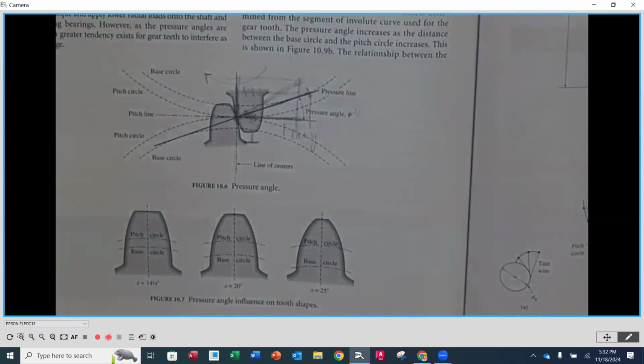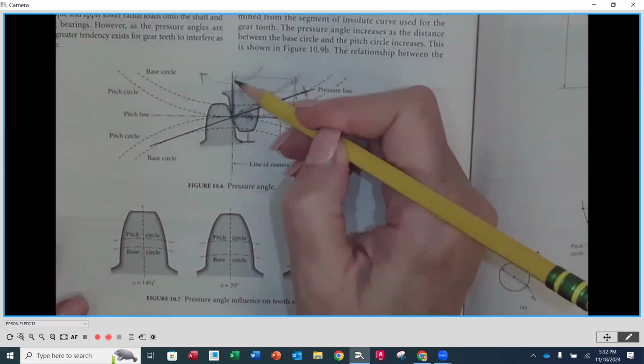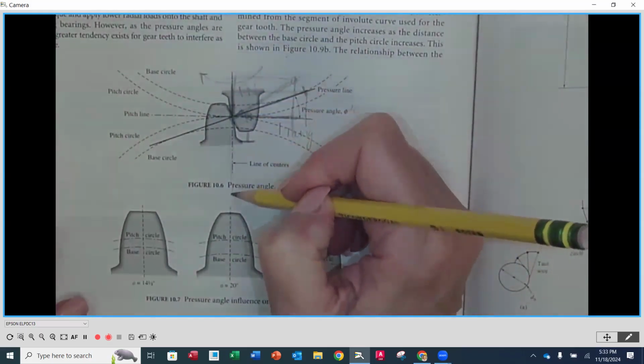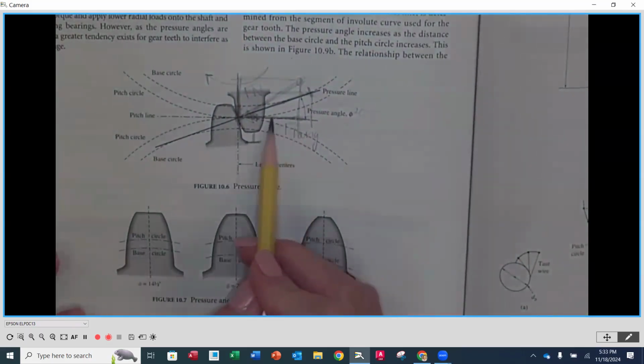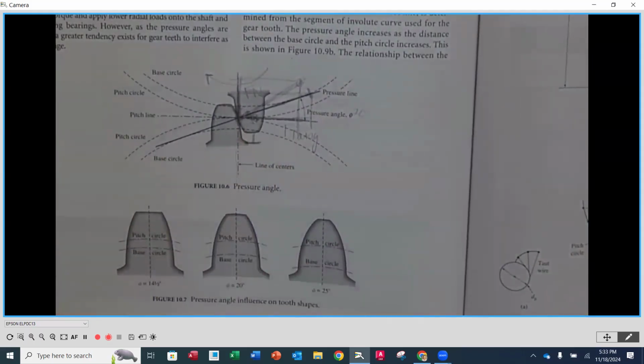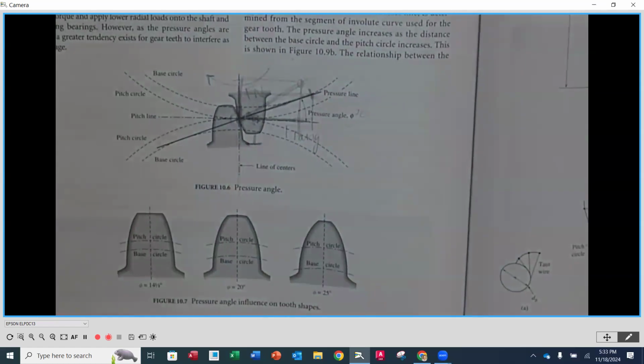The 25-degree pressure angle is reserved for applications where you have really large forces and torques that you're trying to push through, because you're sending more normal force down to the center of your gear where there's actual material, as opposed to putting more tangential force on, which is going to cause the tooth to bend over and the surface to pit away. So when we are anticipating larger, bigger, more robust applications, a 25-degree pressure angle makes more sense.